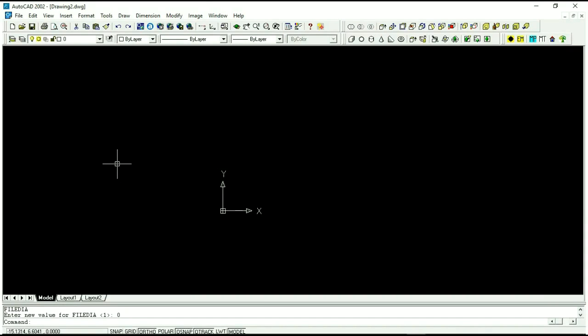Okay, so now I'm going to make those same parts using specification-based design. And so I'm going to make the hip, the joist, the common rafter, and the stud. And I'm actually going to make the first jack rafter on each side of the common rafter on the hip ends. So it's the first rafter that frames into the hip, and so their lengths are 129 and 5/8. One has a left-hand bevel at the top, and the other one has a right-hand bevel.